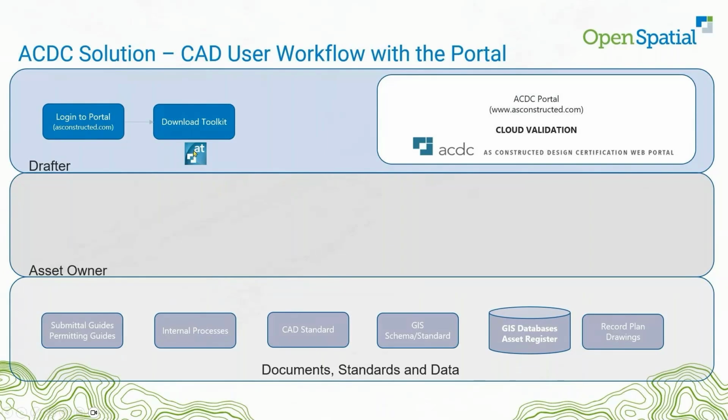That plugin allows you, as a standalone CAD person, to use domain values on block attributes. That's how a drafting person does not need to learn all of the layers and all of the attributes. When you put in the attributes, say for a pipe material, they don't know whether, for ductile iron, you want DI or DIP for ductile iron pipe. Those domain values or acronyms, they have no idea and they're never going to know. But if you provide it to them, then they can.